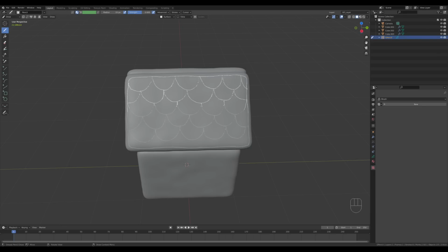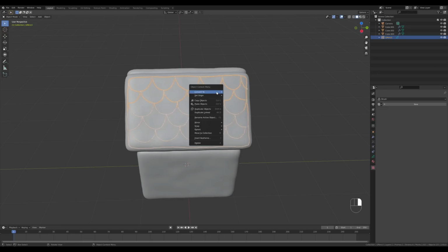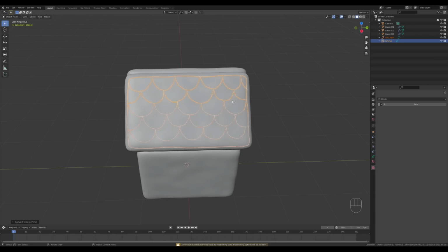Okay, so in the end, I painfully reached out for my pen and did it with a tablet. And now we have this green pencil object and we can exit the draw mode to the object mode. And now, very easy to convert this to curves. Just right click, convert to, and you can choose polygon curve. We'll use some modifiers on it later anyway.